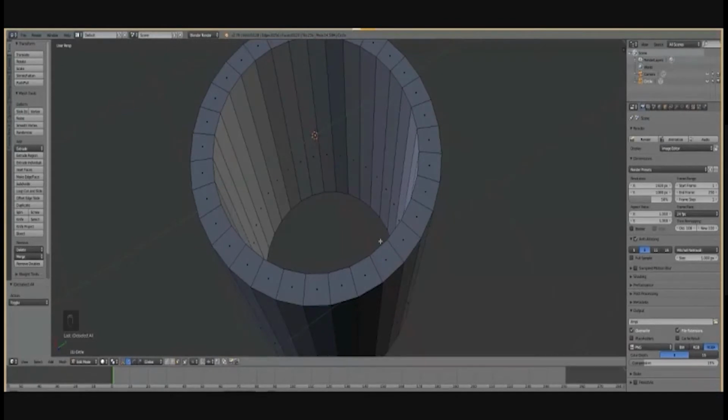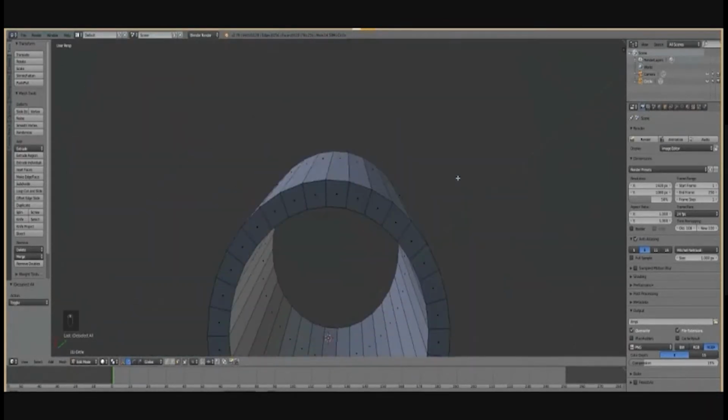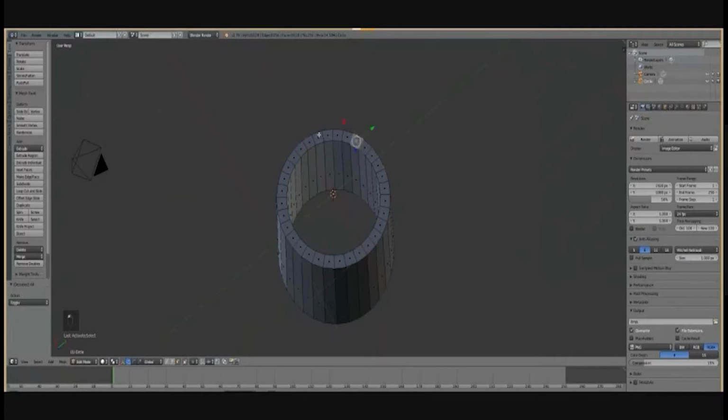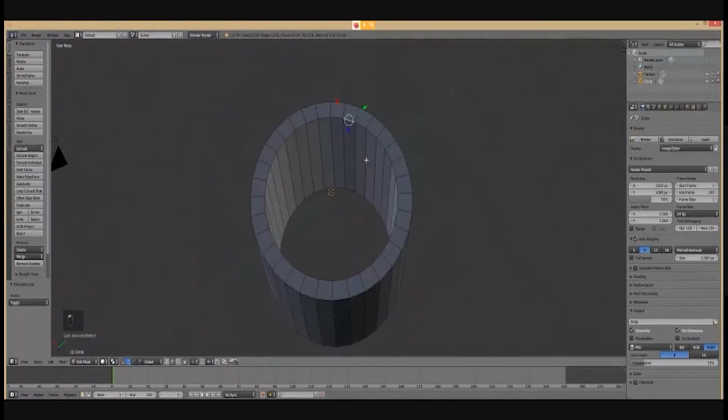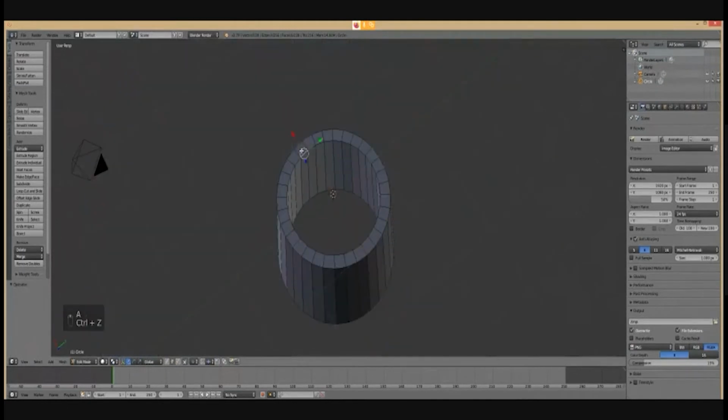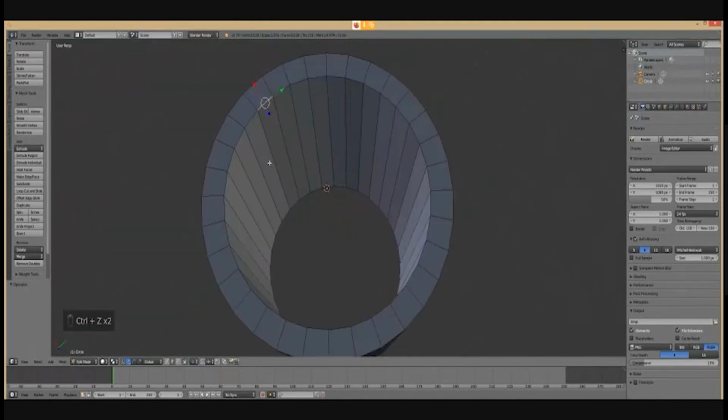And once I've selected those edges, there is a shortcut to just insert a face, right? Right now, if you notice, if I just click somewhere, it's selecting the faces, and I don't want to select the faces. I just want to select the inside edges. So what do I do? I go back to edges, and now I can select the edges, right? So same procedure. I hold shift and then I individually select all of these edges so that I'm selecting the inside circle.